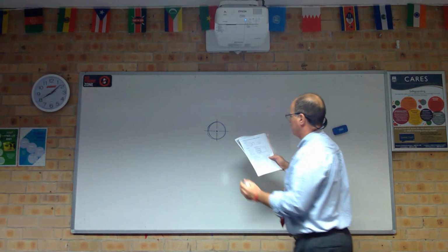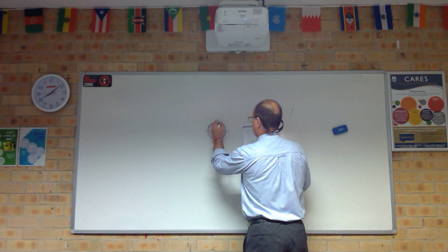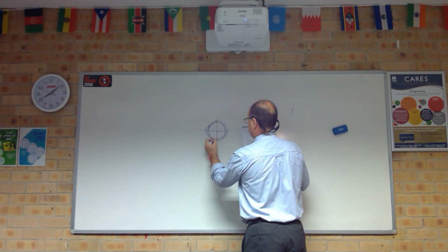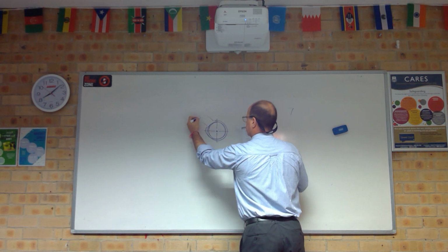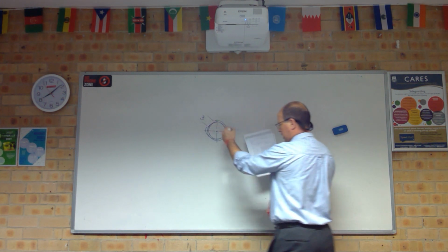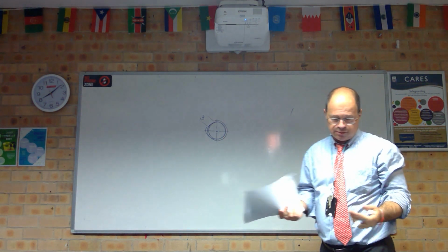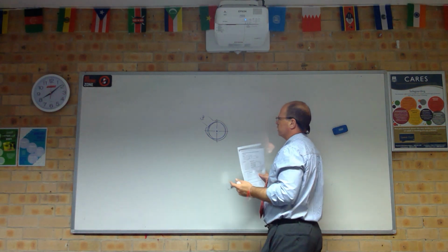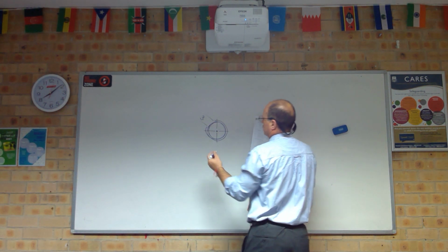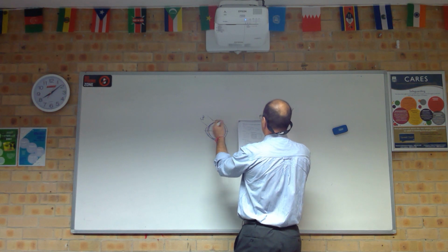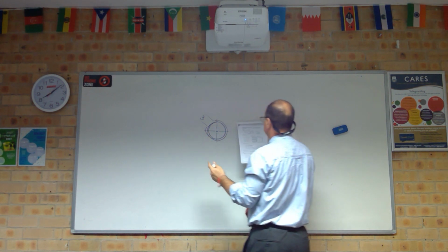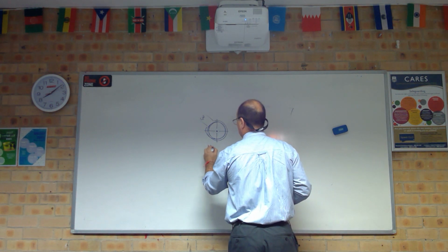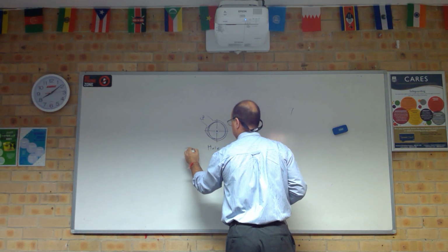And then we go from here all the way around to here. And notice that there's a gap in here. So that's telling you that that is the thread. Otherwise, if you had two circles, you wouldn't know which one's thread and which one's inner diameter and which one's outer diameter. If you look at the one for the actual bolt, the solid circle is on the outside. So this is a threaded hole.